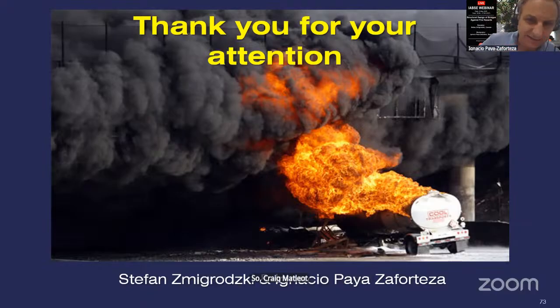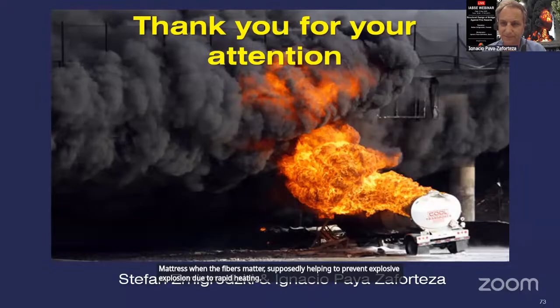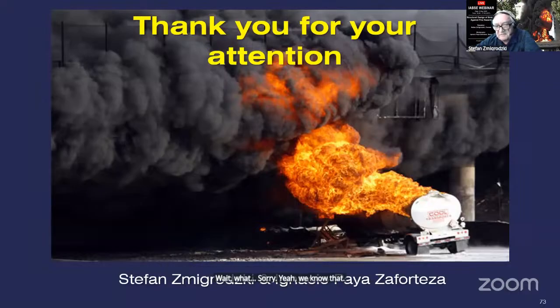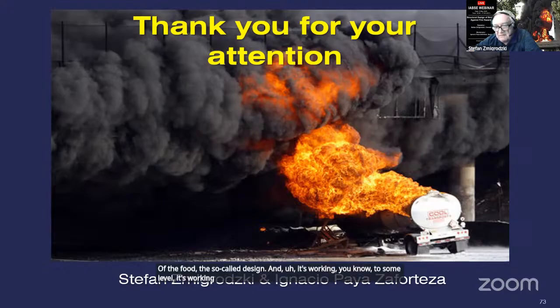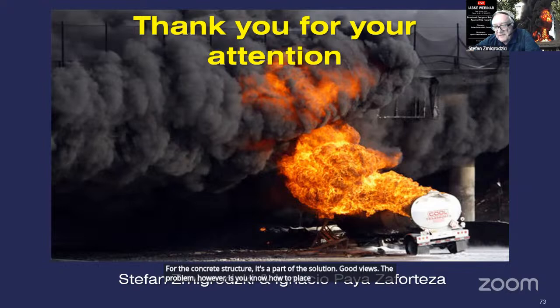Craig MacLeod is asking if you have looked at the use of polypropylene fibers in concrete mixes for mitigation. These were used on tunnel-type bridges in Windsor, Canada, on a new highway to allow moisture to travel through the concrete matrix when the fibers melt, supposedly helping to prevent explosive spalling due to rapid heating. Yes, we know that, it's part of the design, and it's working to some level. For the concrete structure, it could be used as part of the solution. The problem, however, is how to place the fibers, because they have to be concentrated in the part exposed to the fire. So the mix should be carefully prepared, and the placement as well.